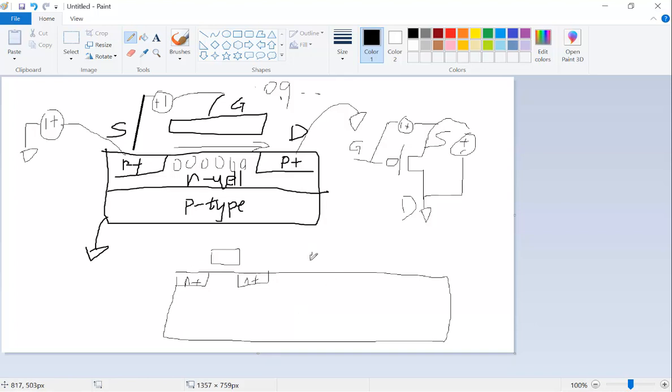And then you got a PMOS just next to it, like the inverter, right? You have a PMOS on the top, NMOS at the bottom. I actually have a lot of PMOSes very close to NMOSes. So you got a PMOS over here, also has a gate. And that's P+. However, this guy has to be in the N-well, right? Just put N-well here. You know how to draw N-well. We have done that with a resistor, right?